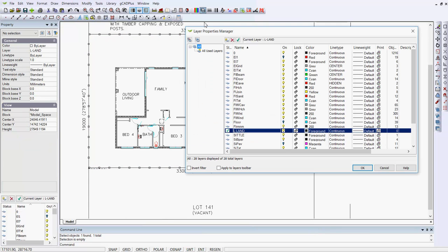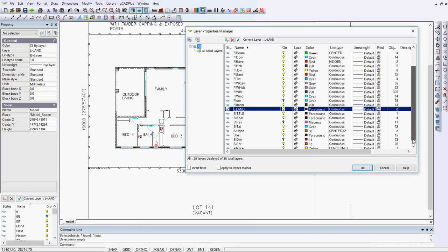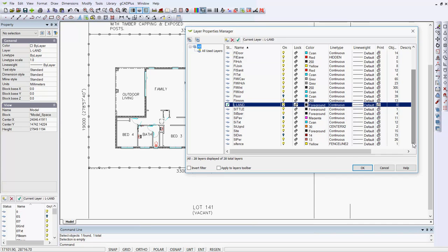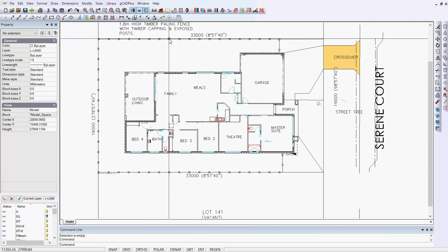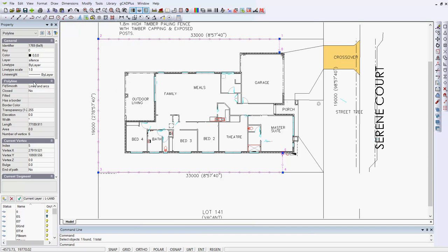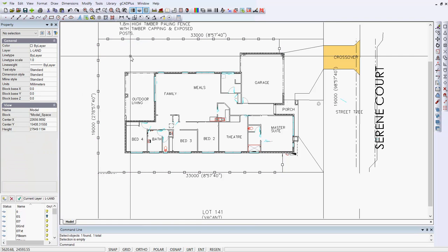Now we have to come over here to layer SI Fence, and I think we'll find that it's got a particular, here it is right at the bottom, it's got fence line 2 associated with it. So that's why it's being drawn with the simulated posts in the fence. You could pick it and quite possibly change its line type scale. And if we make that 1.5, that spreads the markers on the fence line out a little to look a little more realistic. So I hope that shows you a much easier way of working on a base drawing that an architect gives you. We now have a very clean environment and we can work happily with it.